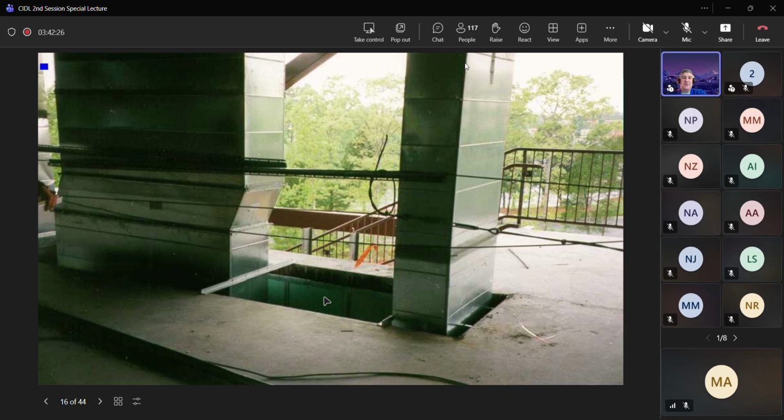But we link this to the design. In fact, architects in the UK came up with a solution for this, where they put a rigid type of plastic covering that can then be cut out with a utility knife and things of that nature. So when the different contractors come, you can imagine a hard plastic sheet goes in here to cover these holes before they pour the concrete. And then when the utility people come, they just cut out their particular hole.